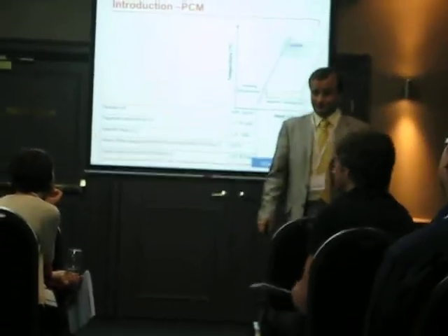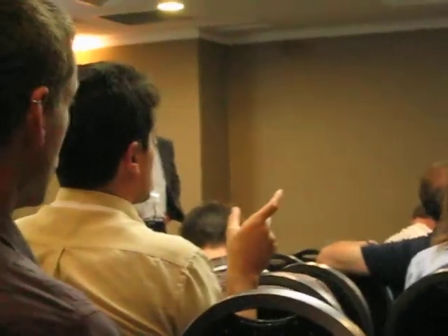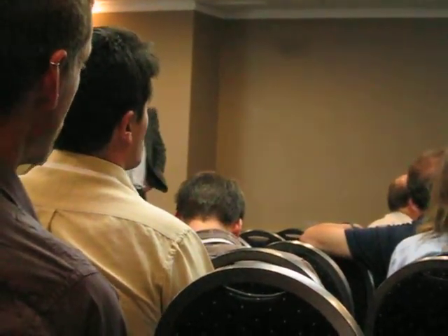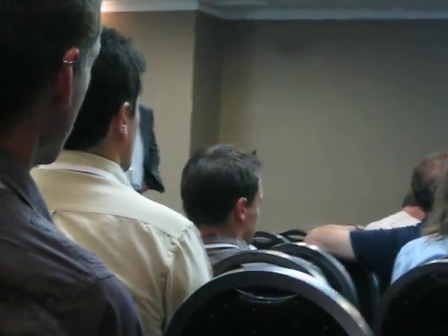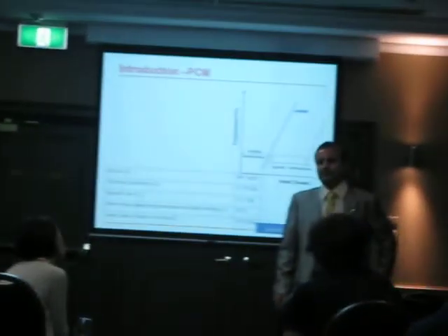That's quite a gap between 1 millimeter and 10 millimeters because the phase change material doesn't conduct heat very well. Conductivity is not good. Yeah. You might find that you don't actually access the heat capacity of the phase change material further than a few millimeters deep into it. In reality, we know that.